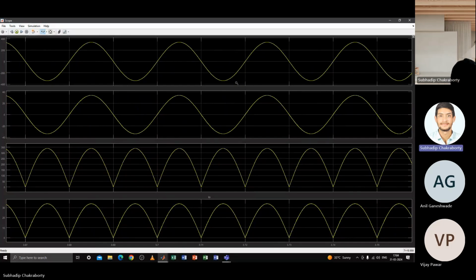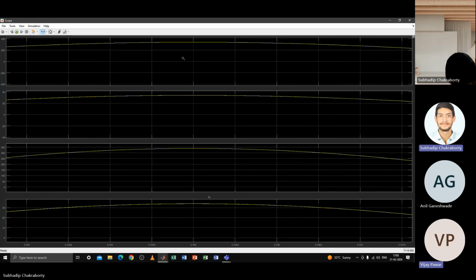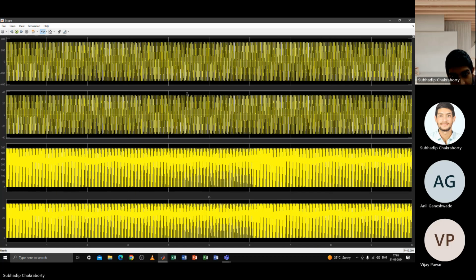Seeing these two waveforms of the voltage and current, what is the definition of, I can say, displacement power factor? So do you see any overlap? Since the voltage and current both are sinusoidal in nature, no question of distortion factor. Okay. So power factor comprises two terms, distortion factor and displacement power factor. Now, since we are talking about sinusoidal waveforms, our distortion factor is unity. Okay. So what can you comment about the displacement power factor? Do you see any phase shift between input voltage and current? No. They are in line, right? So they are in line means that the power factor is unity.